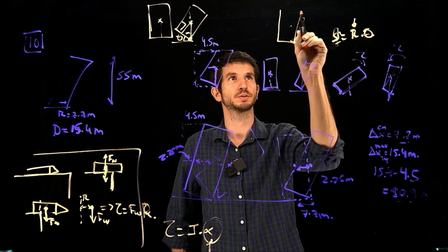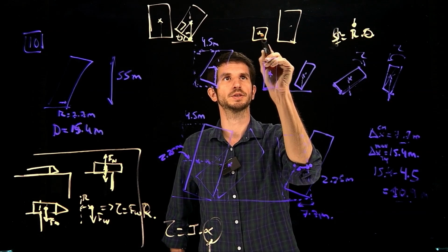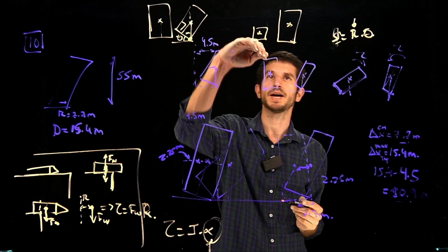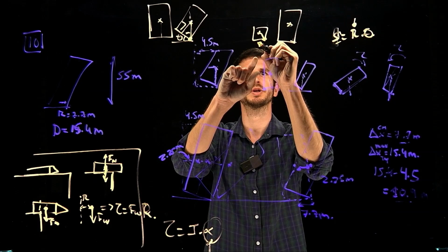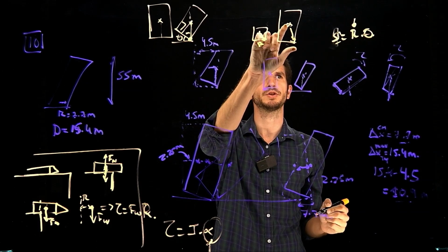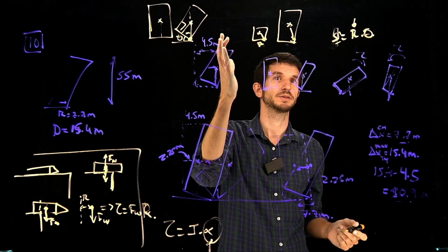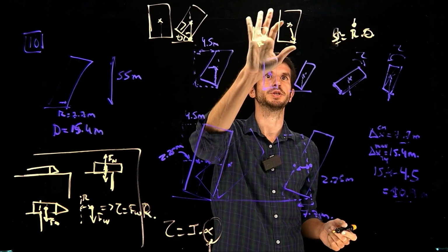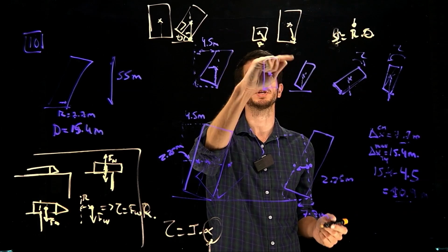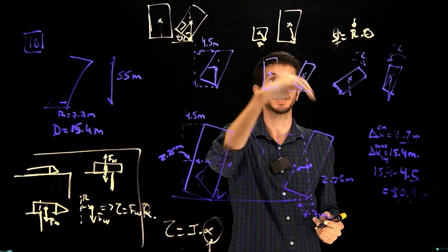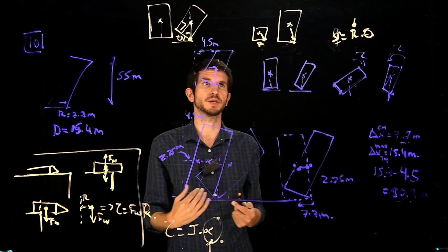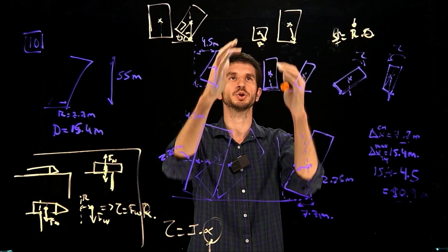let's make this, and let's make this. The center of mass is here, the center of mass is in there. As I start to tilt, this is going to be the radius, and it's going to be, if you wish, the distance. So that distance is higher, right? So that's going to be much easier to get out with a displacement out of the base, whereas in this case it's not. So ways that you can increase stability: increase the base, but also bring the center of mass down.